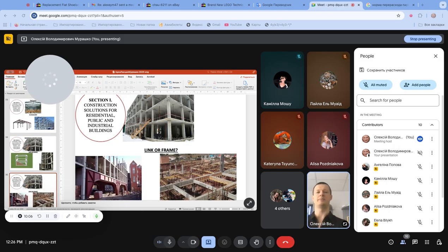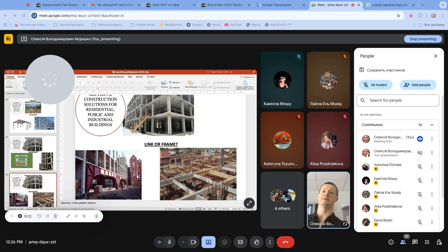And sometimes it is possible to make a mixture of these methods. So, for example, on the first floor of such a big building, to make big spans, they have designed metal frames which serve as a big frame for the longitudinal direction of this building. Also, this frame serves as a beam, not a redistribution beam.